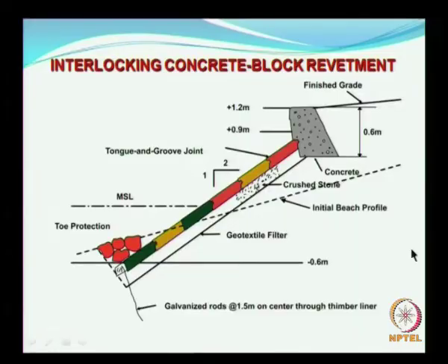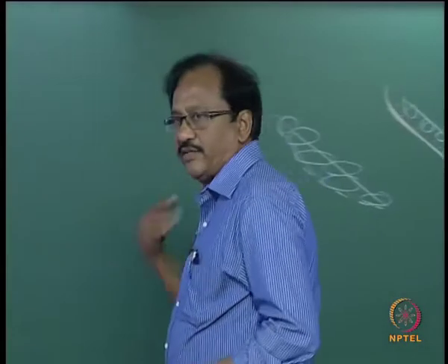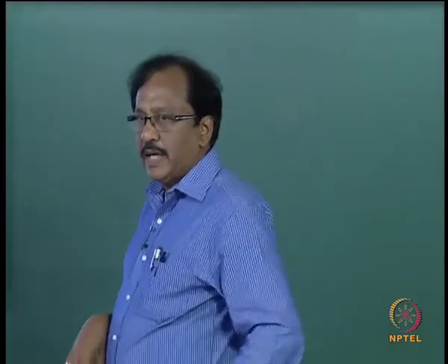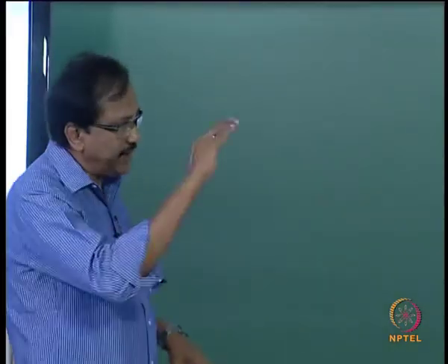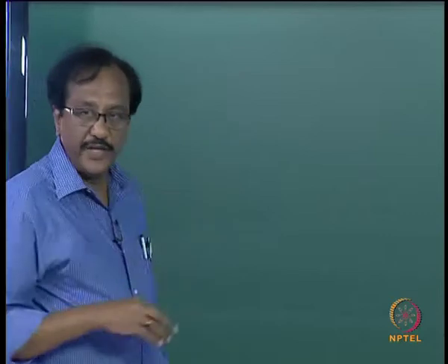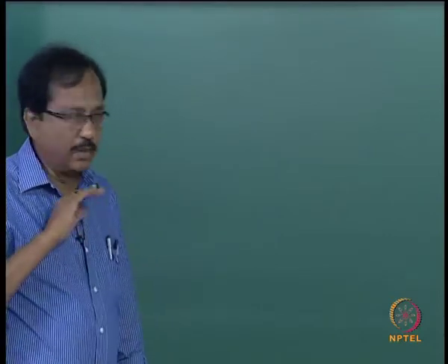But the only thing is, you have to be careful in providing a strong toe protection. Although there are some advantages, like from an aesthetic point of view it is very good, where you do not have many projections as in the case of rubble mound, and it has a nice finish, and it gives a good look.